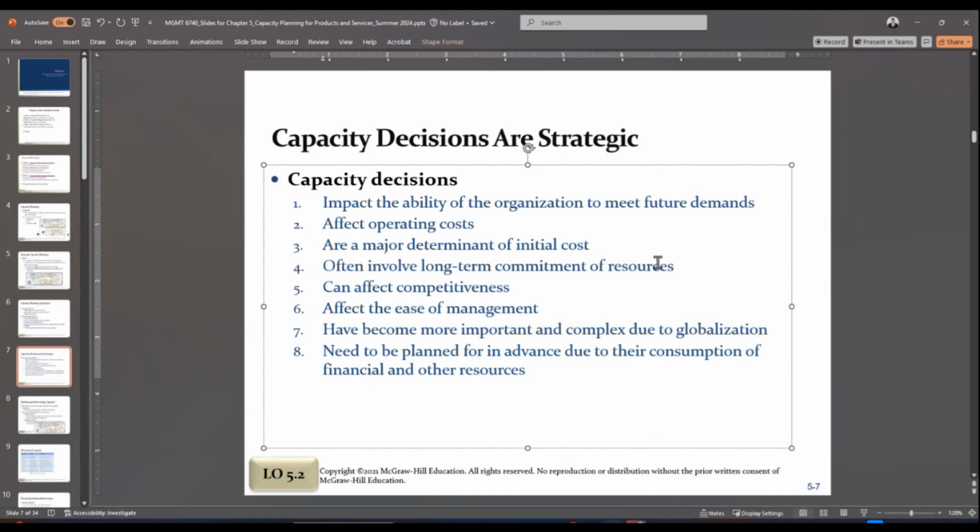Suppose there is a big machine that does everything for $1 million, and the payback period is anywhere from 3 to 7 years, versus you go with 3 smaller pieces of equipment. So instead of $1 million, maybe each of those costs you 200K, and the payback is say 8 years. Something like that, because it has high operating cost, more operators are required, more consumables are required, and so on. So balance out the risk and benefits, pros and cons, cost and benefit, and make the right decision.